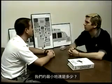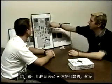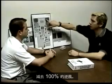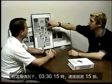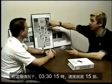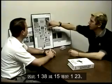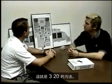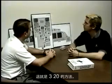What would be our minimum ground speed? Well, minimum ground speed is calculated by taking your V approach and then subtracting out 100% of the headwinds. And in this case, at 330 at 15, that'd be 15 knots. So 138 minus 15 is going to be 123. That was V approach for the 320.